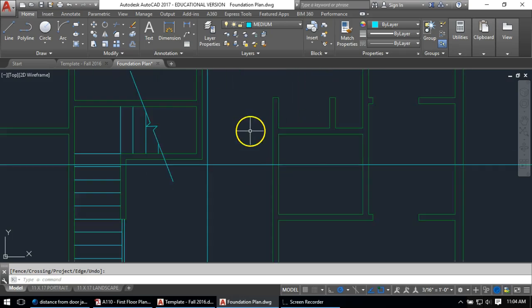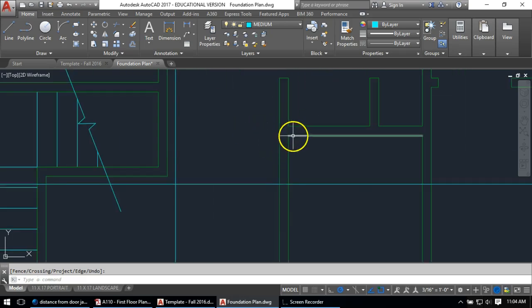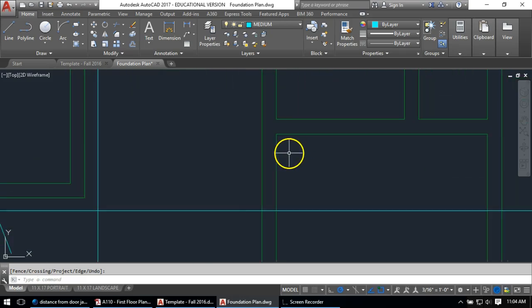Let's see, there's a door up in here. There's no dimension on it, so I'm going to assume we were offset 3.5 inches, or even 3 inches could probably work. But I'm going to do 3.5 because that's what I said earlier. So offset that. I'm going to come down 30 inches.